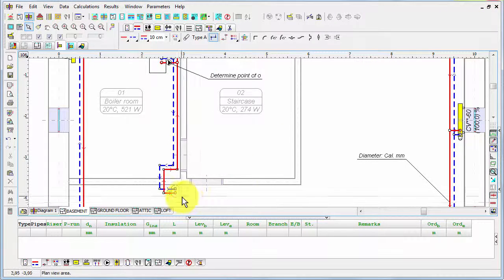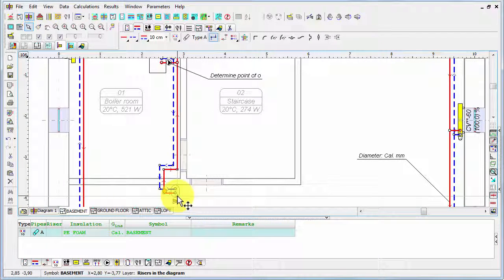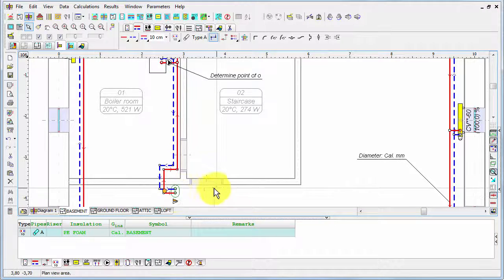Because we put the riser, but this tool, this element, in fact, is the riser in the plan view. To have a real riser in 3D, we need to put these elements on two floors in the same position. To maintain the same position, a very easy way is to use copying.